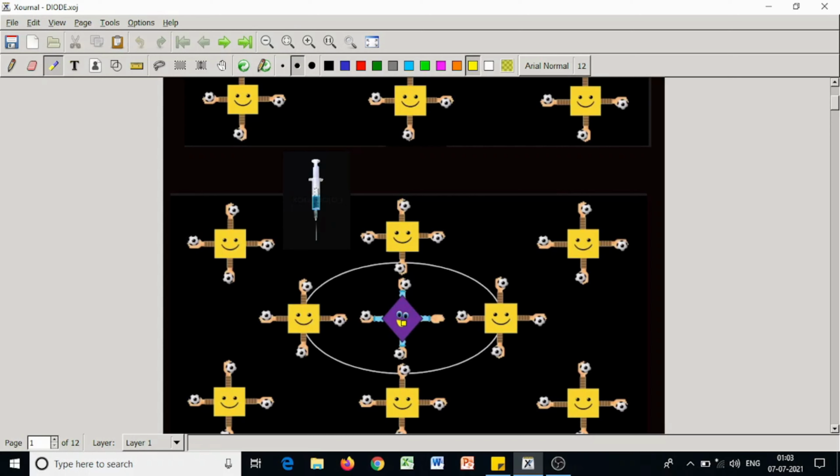This is the aluminium atom having 3 outermost electrons forming covalent bonds with neighboring silicon atoms. But it lacks 1 electron to form the 4th covalent bond with the 4th neighbor. The vacancy that exists in the 4th bond constitutes a hole.